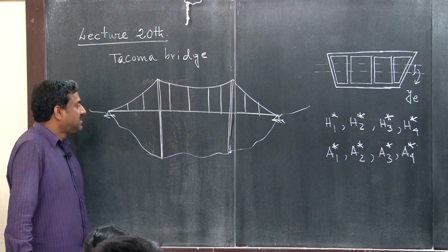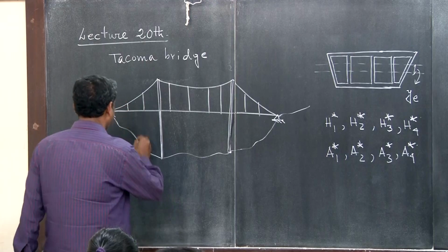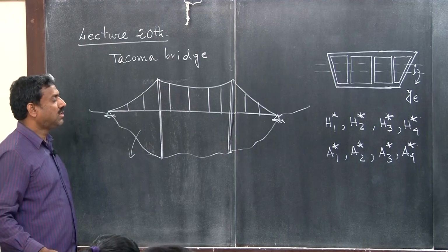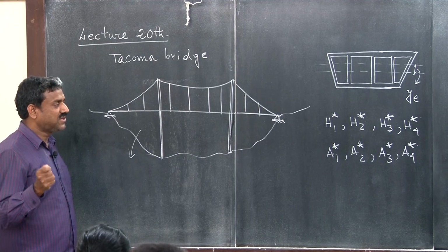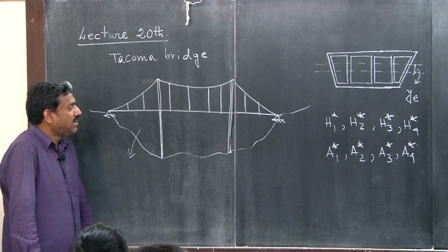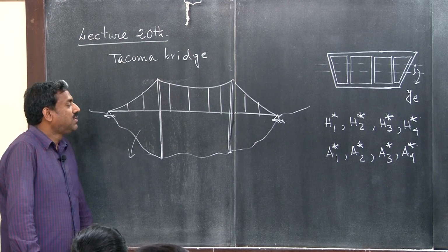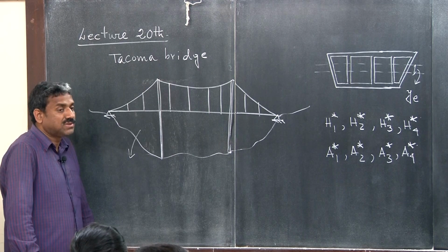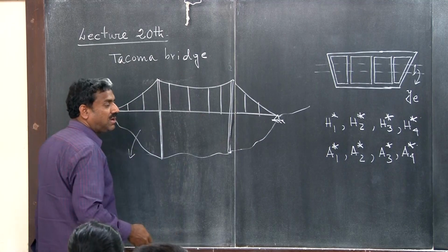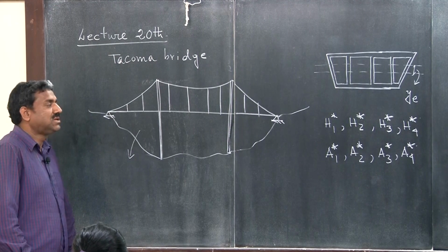This was a cable suspension bridge, and we considered a reduced order model for it, the kind of model we also use when testing in a wind tunnel. Even though we have a good predictive model, we always want to do numerical and physical modeling, experimental modeling, and test in a wind tunnel to check the critical velocity for flutter. There we use a sectional model. We consider a beam model with equivalent properties scaled, referred to as an aeroelastic model, with distributed elasticity.